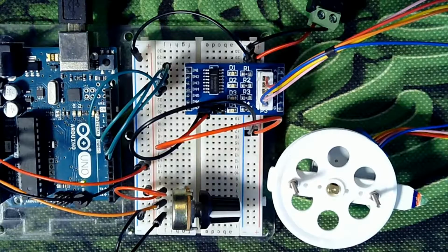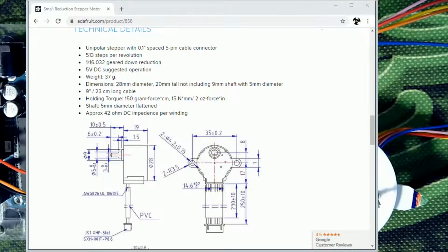So let's take a look at what the stepper motor is. We're going to have a better look at what's happening there. This is some detail specs on the stepper motor itself. Basically, up here is the can itself, measured in millimeters in this case. So we have ourselves a small can. It's not too big. It's got a shaft on it that's 5 millimeters in diameter, a very common size, with 2 flat sides to it, so you can put something down and lock it on with a set screw. But here are the details that we really need to care about right now, with some of the electrical details as well.